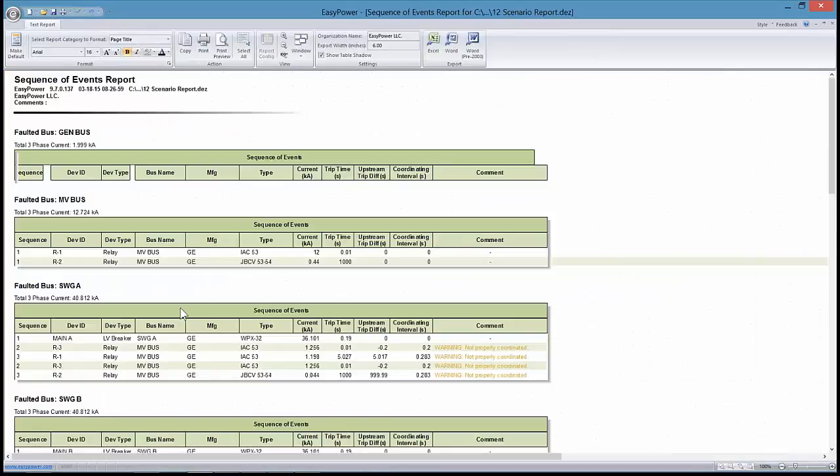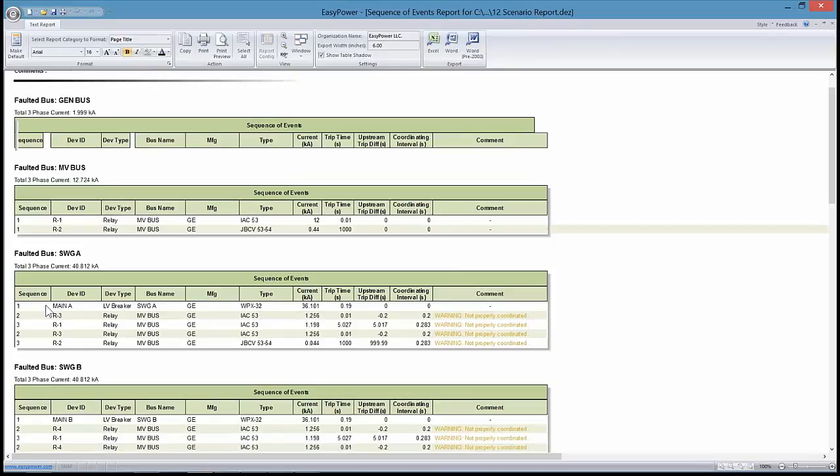As we look at a specific faulted bus, you can see that there's current actually flowing through a number of breakers that we may or may not consider in series with wherever that fault is. You can see that relay 3 is being affected through a couple different routes, and therefore just adjusting one connection through that route may not really reduce the incident energy or the trip settings that I'm trying to deal with.